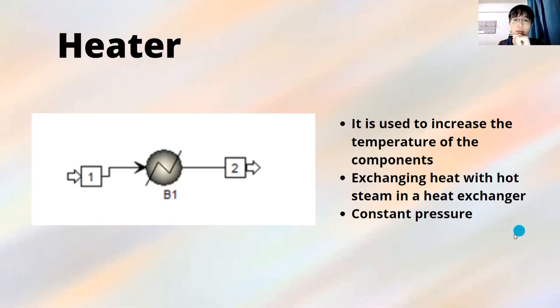In addition, a countercurrent shell and tube heat exchanger will be used as our heater instead of an electric heater. This is because the heat exchanger has lower operating costs but produces the same heating effect as an electric heater. Therefore, it is more preferable. However, if high temperature is required, then an electric heater might be a better choice.